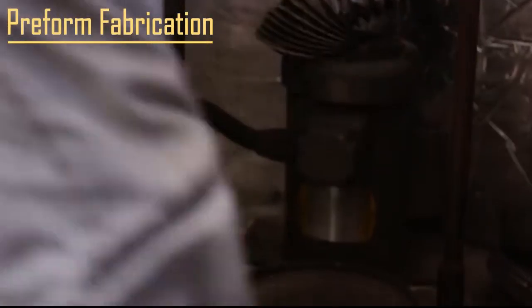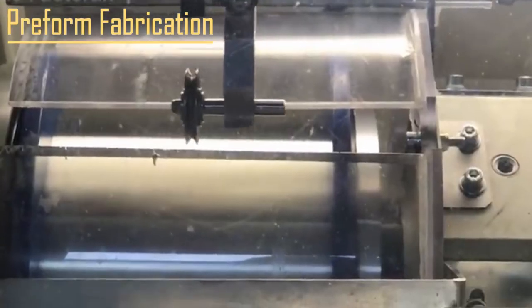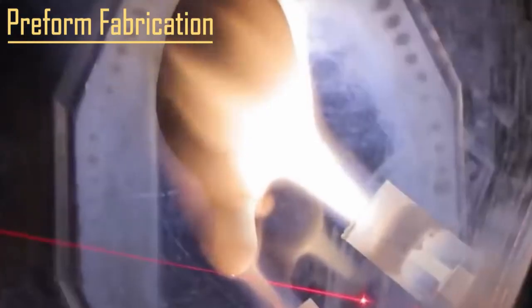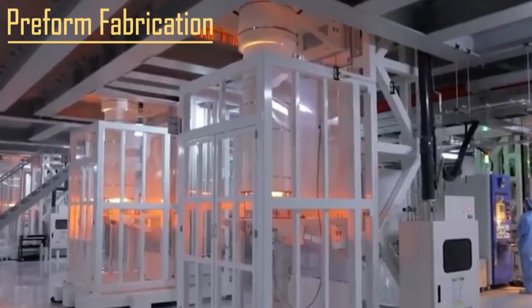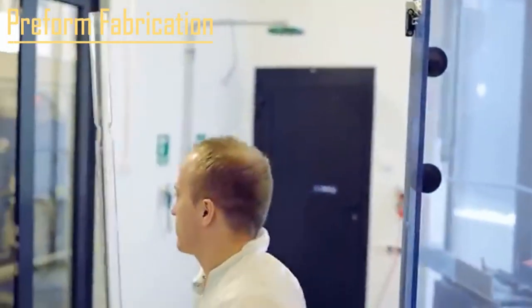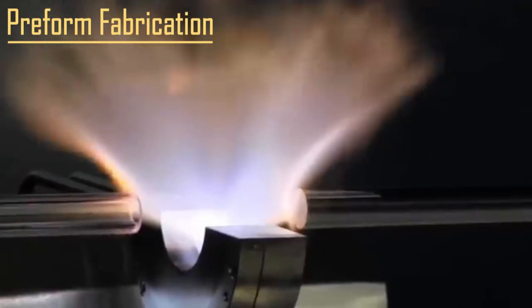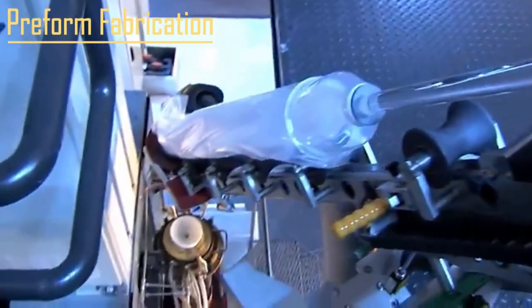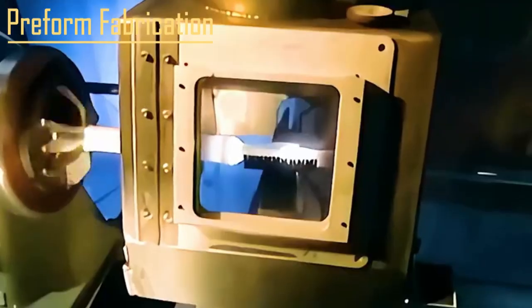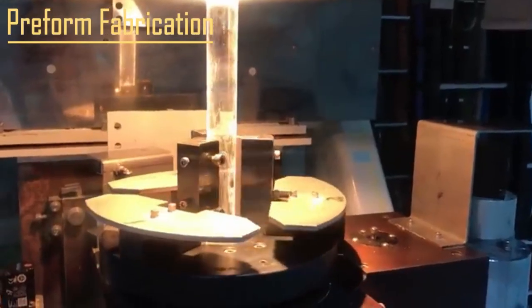Instead of melting sand into a solid block, technicians convert the silica into gaseous compounds under high temperatures. These compounds react and condense into layers of ultra-pure glass inside a slowly rotating, hollow glass tube. As the glass is built up layer by layer, engineers carefully adjust the gas composition. This determines which section will become the inner core, the light path, and which section will form the surrounding cladding. The thickness and purity of each layer are tightly controlled, as even the slightest deviation can compromise light transmission.